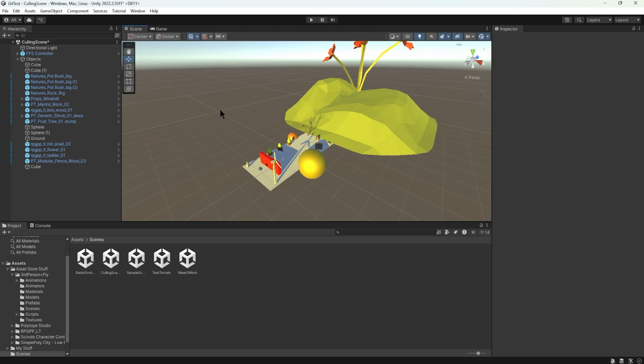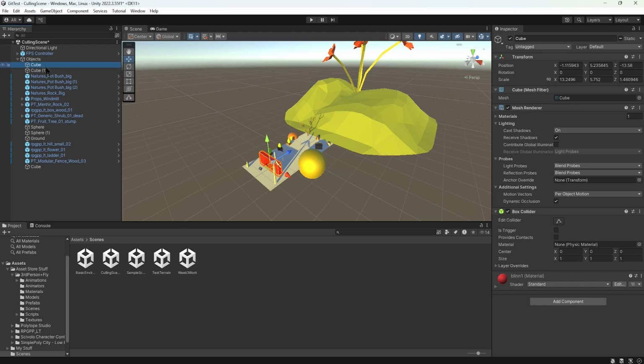When it comes to your work with occlusion culling, always just check both of them off. Occluder and occludee, just check both of them off all the time. There is no reason to not be checking both of them off all of the time. The formal definitions of occluder and occludee will be available to you on the course website, but in reality, you just want to check both of them off. There's no reason not to check both of them off in most cases. There are a few objects here and there where you absolutely do not want to check off occluder and occludee.